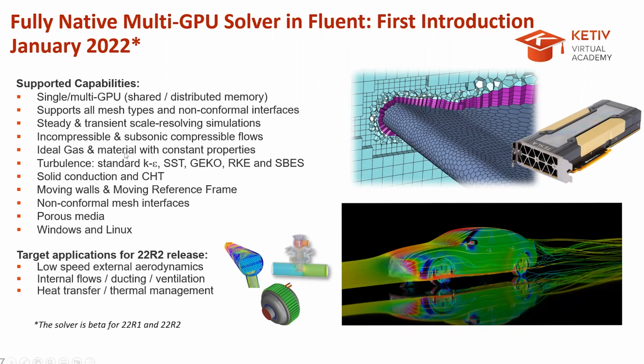Both steady and transient simulations can be done. You can do incompressible simulations as well, and then subsonic compressible flows as well. Constant properties for materials or ideal gas properties are supported in the native multi-GPU solver, and a lot of the turbulence models are covered as well, including RANS models like standard, realizable k-epsilon, generalized k-omega, or even LES simulations and LES hybrid RANS simulations as well.